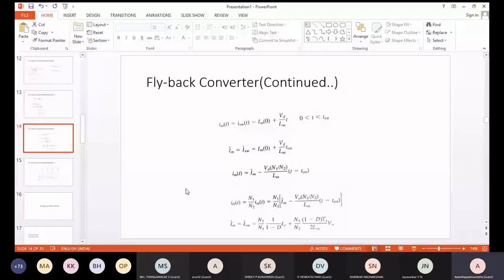At this point of time, I just want to highlight the fact that once we design any converter, either buck converter, buck boost converter, or flyback converter, you are going to use the design principles, and you will arrive at the values of L and C. Once you arrive at the values of L and C, when you simulate, you will see what the expected current waveforms and voltage waveforms are, mainly across the capacitor and through the inductor, and whether they are matching. That's what we have to know. The other controlling parameters are obviously the duty cycle, the input voltage, and the load current.